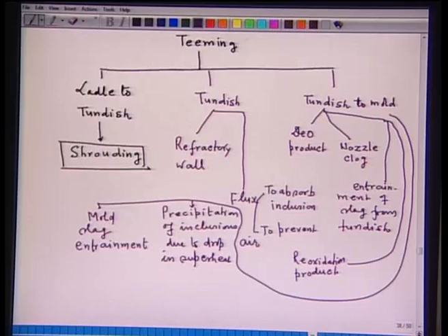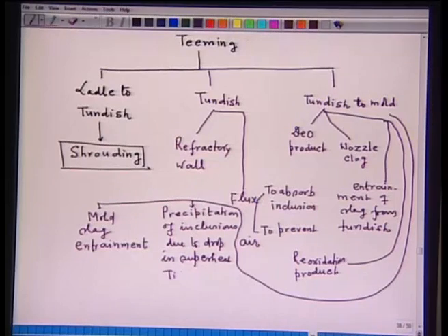Now, when the superheat drops or when the liquid steel cools, it solidifies, then depending on the solubility limit, the elements in the steel can combine and an inclusion can precipitate. For example, say TiO2 in say titanium treated steel.